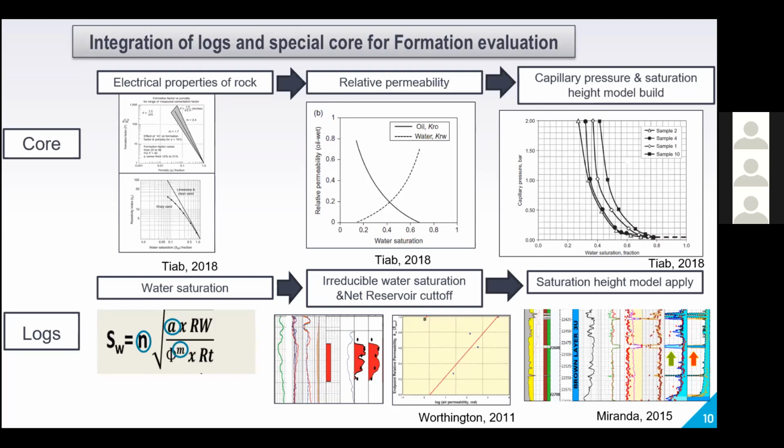The extracted water is measured as a volume of water saturation. But when I am injecting the gas, I am injecting it with a capillary pressure called PC. So I make a relationship between capillary pressure and water saturation. For every reservoir, they will be different. Based on capillary pressure and water saturation, I use them in some mathematical models, for example the J function, to start to construct an empirical relation between the water saturation and J.